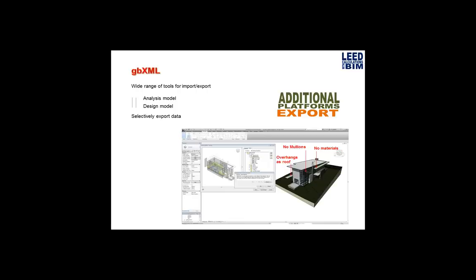For the analysis model, a good rule of thumb is to keep your geometry as simple as possible, and that's one of the other reasons I suggest you create a separate model that will go to the export and then be handed off to an engineer or someone who's going to be doing the energy model. That separate model is an effort that somebody has to maintain to match the form of the design. Yeah, it has to stay current. The designer's changing the form of the building, so the simple energy mass of spaces has to be updated manually.